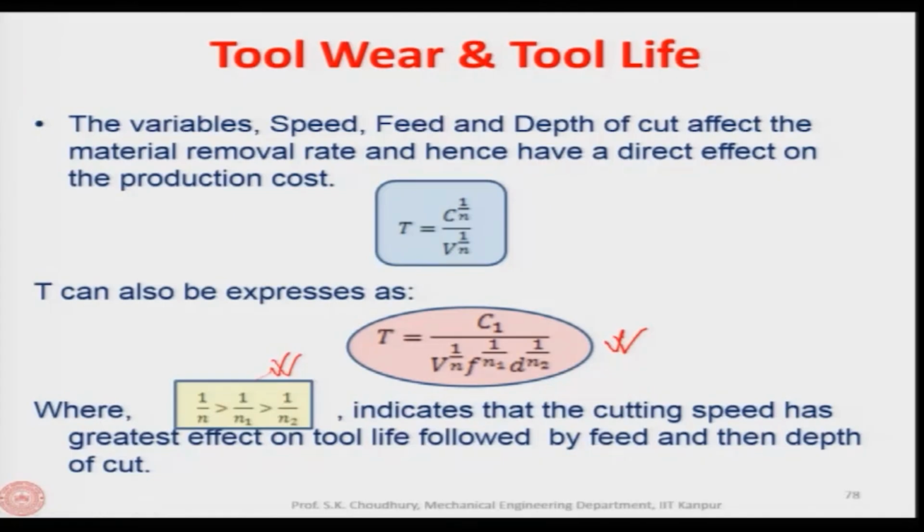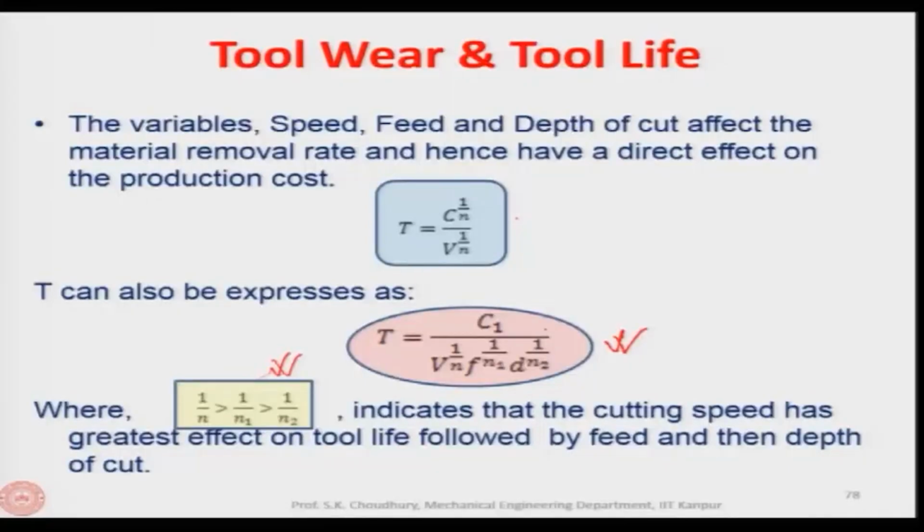So, this is an important formula, because it is sometimes called the extended Taylor's tool life equation, where the tool life is related to cutting velocity, feed and depth of cut, whereas Taylor's tool life equation relates the tool life with the cutting velocity only, because Taylor did that long time ago, when he did not have the computer facilities and the proper experimental facilities that we have right now. So, afterwards the extended Taylor's tool life equation related the tool life with the cutting velocity, feed and depth of cut. The rest of it we will discuss in our next lecture.